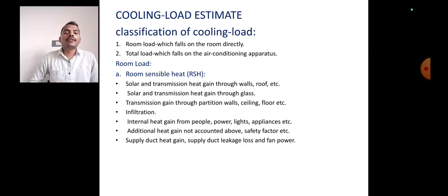Next, additional heat gain not accounted above. Safety factor. Safety factor means we calculate the total amount of cooling load, or heat entering the room, but the maximum possible condition does not always occur. In some conditions, like peak summer afternoon, more heat is transferred from the wall to the room.